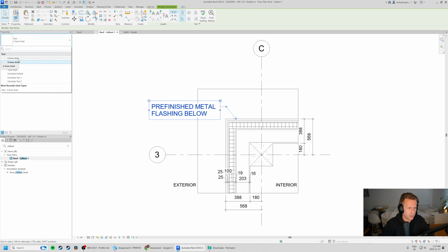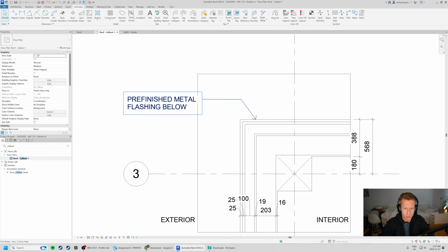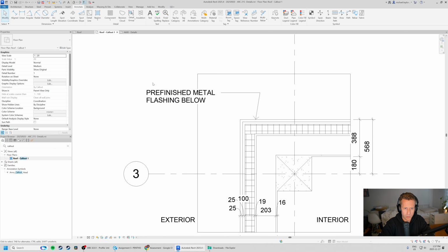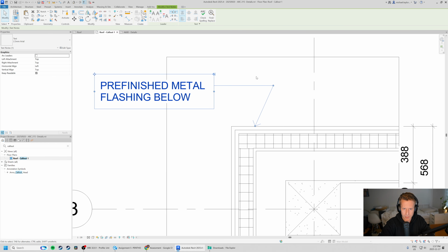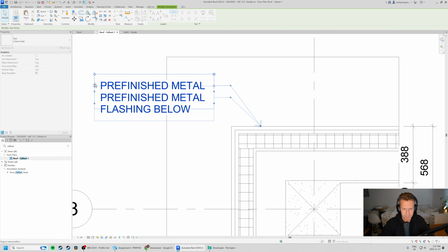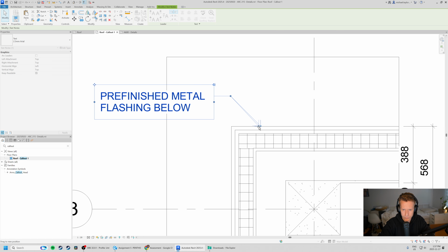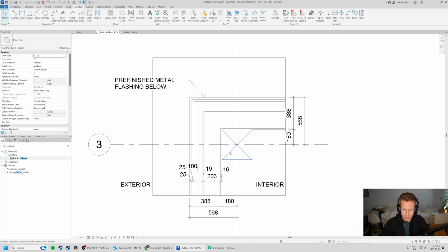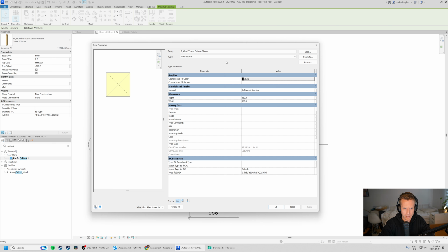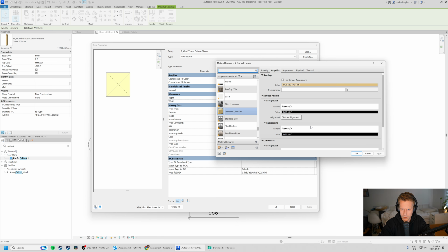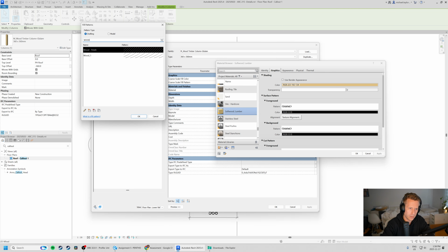So it's looking a little beefy. Let's turn this down to 2.5 millimeters here. Once we've got this note, if we click on the note, we can kind of move it, right? A little frustrating, but while the note is selected, we can also modify the arrows here, blam, something like this. Cool. One thing I should change real quick here is why this is reading like concrete. Interesting. So it says softwood, but that is not the pattern that I would use for softwood.